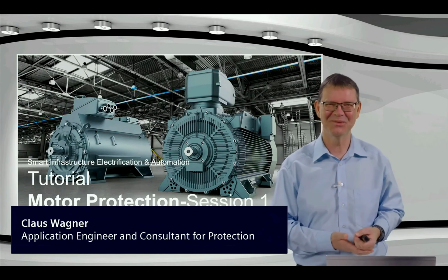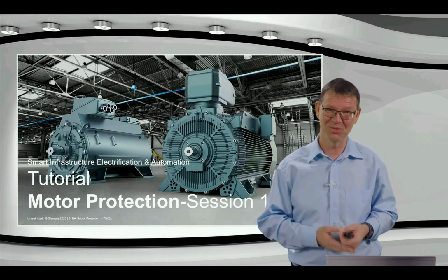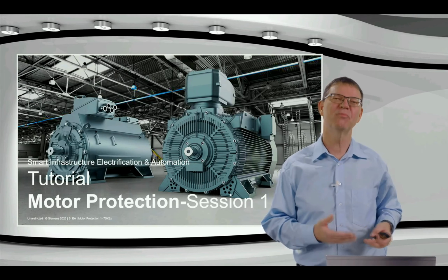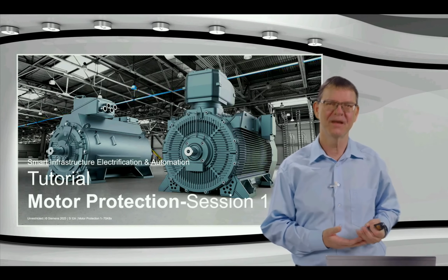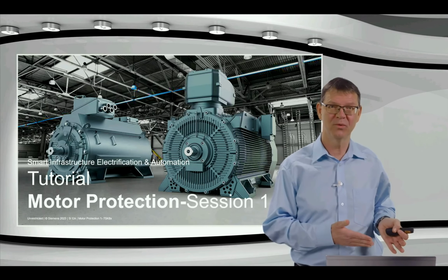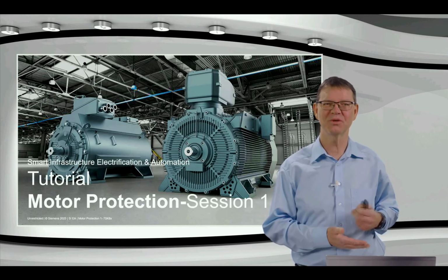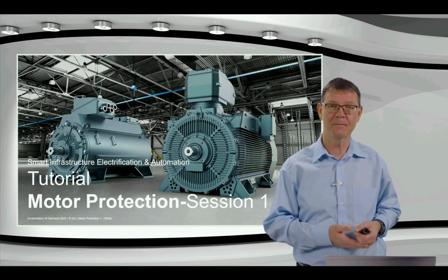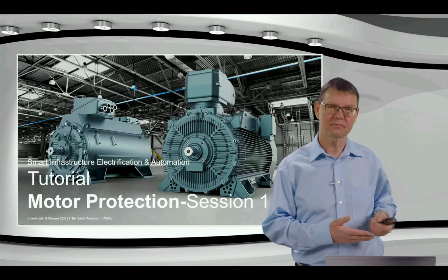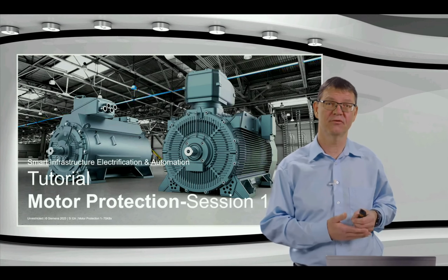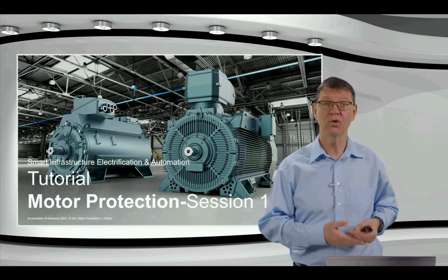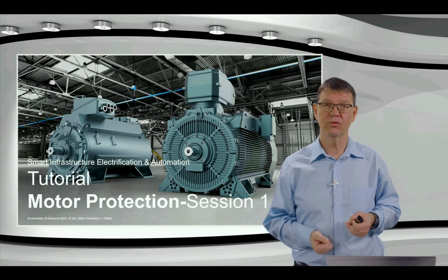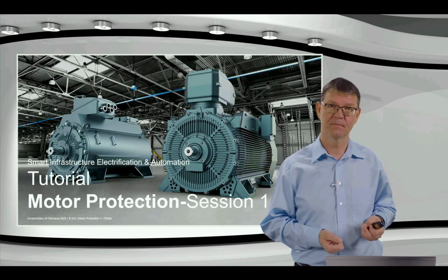In this tutorial, we would like to present and discuss the motor protection functions of SIPROTEC 5 in detail. We've planned in total 2 sessions. In the first session today, we will talk about various aspects of short circuit protection and the thermal overload protection for the stator. In the second session, coming on the 2nd of May 2023, we are going through all aspects of thermal protection of the rotor and also show you additional functions and handling features.